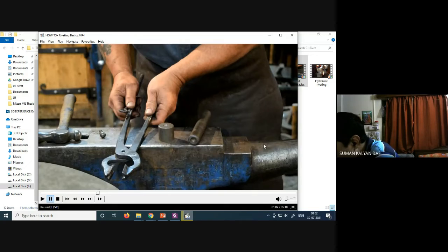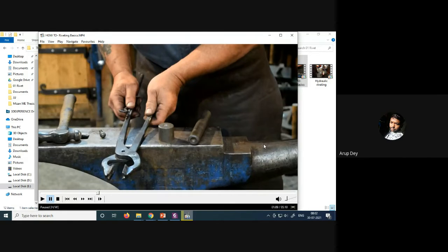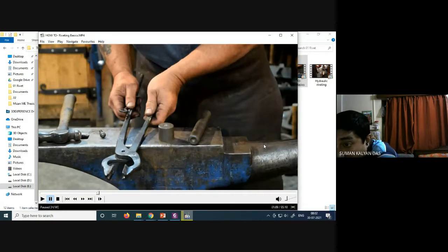Now, actually, the rivet is normally made of the same material as the plate. I gave the example of that vessel, the aluminium vessel in which rice is being cooked. Normally, it is a thumb rule that the rivet is made of the same material as the plate, not of a material of lesser strength than the plate. That actually is what I meant. Okay, sir. What material of the rivet you select should not be of lesser strength than the plates that you intend to join, because that is definitely not a desired scenario.